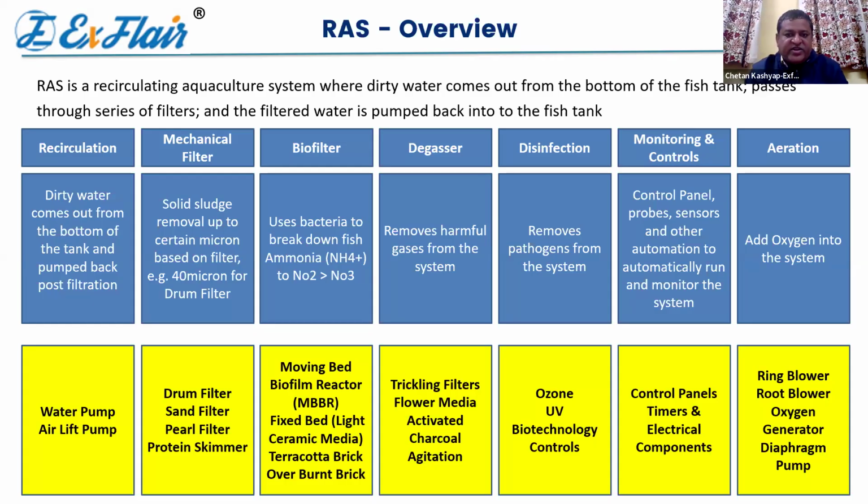For example, in case of a drought, or in some foreign countries like Kuwait, Oman, where we have designed systems, they have very high temperature and very high humidity. When the humidity and temperature are high, the blowers and all are not very effective. So in those cases we have to use an oxygen generator as a backup. Okay, I'm moving to the next slide.